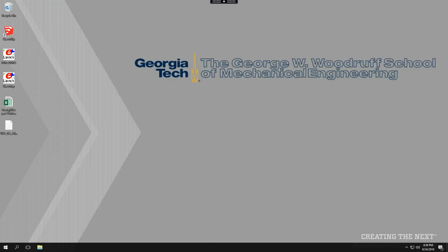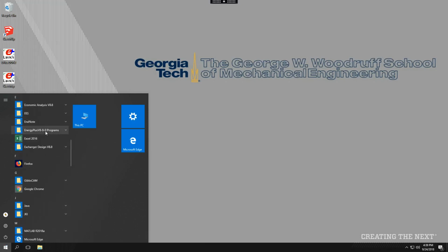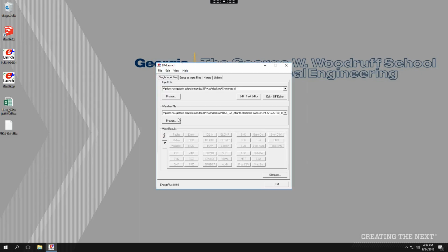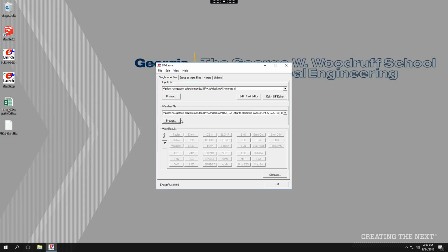This is the first part of the EnergyPlus assignment. On VLab, you can find EnergyPlus here, and then go to EP Launch. You're going to need to select the weather file that was provided. You should probably just put that on the desktop of the VLab to avoid any issues.